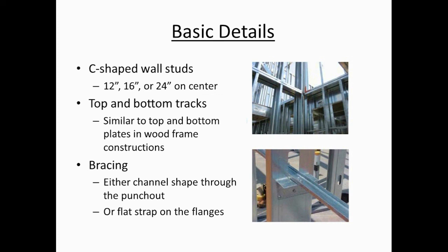In a non-load-bearing application, typically the wallboard gypsum panels installed on both sides of the C-shaped stud are sufficient to resist that rotational tendency. In structural applications, sometimes a structural member experiences more stress under construction loads than it ever will under the design loads or the actual in-place loads. That means that this stud will be under load prior to the gypsum board providing the lateral bracing.